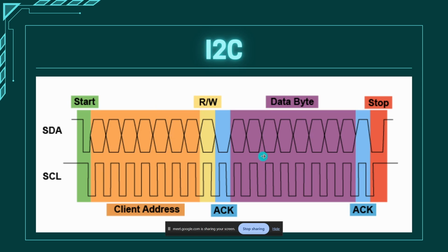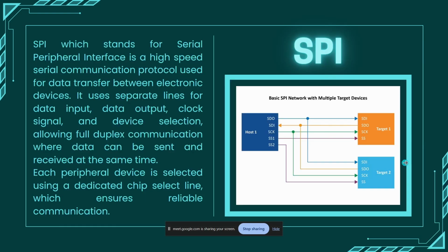I2C is like, this is the address which I want to talk to. But this guy, he's a giga chad. He will directly go to the module and put some signal called chip select. It's a single bit value. If the chip select is one, that chip is selected and he's talking to that. So SPI is like a giga chad who doesn't bother using addresses. He uses chip select.